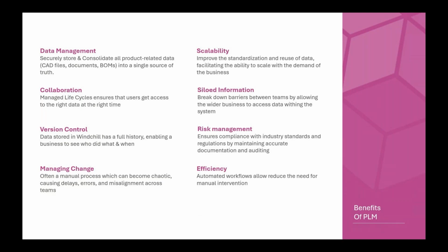With Windchill, we can track the full life cycle of each part. So you can identify what state a part is currently in, whether that's in work or a prototype stage or whatever that may be. We can identify what changes have been made, who made them, when those changes were put in place, and maybe where that part is used within the business. What products does it end up in? What manufacturing processes is it involved with?